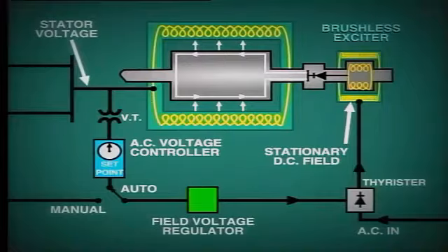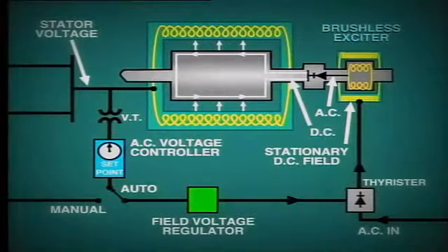The rotor winding produces AC voltage, and this is fed directly into diode-type rectifiers, which are built into the shaft. So we have, in effect, a rotating rectifier. The DC output from the rectifier is connected directly to the main rotor winding through leads which pass inside the shaft. There is no need for collector rings or brushes.